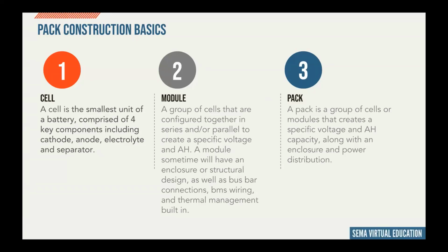And from there, we use the combination of cells to build either modules or the battery pack. So the second level inside of a battery pack is a module. Battery packs don't have to have modules, but a module is a great way to break up a large pack with high voltage into smaller sections that are easier to work with. They're easier to handle and load into a battery pack during construction, and they're easier to use as a building block for different battery packs. If you have one module, they can be configured differently, and then they can be built into battery packs.